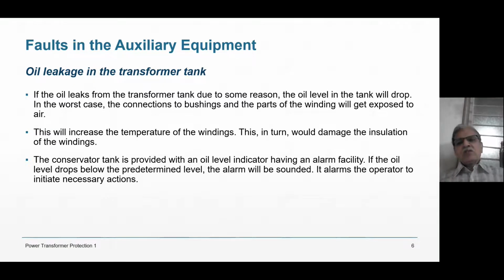Therefore, you see all transformers with the conservator tank, one pipe is connected, and that pipe at the end, there is a device in which silica gel is filled.